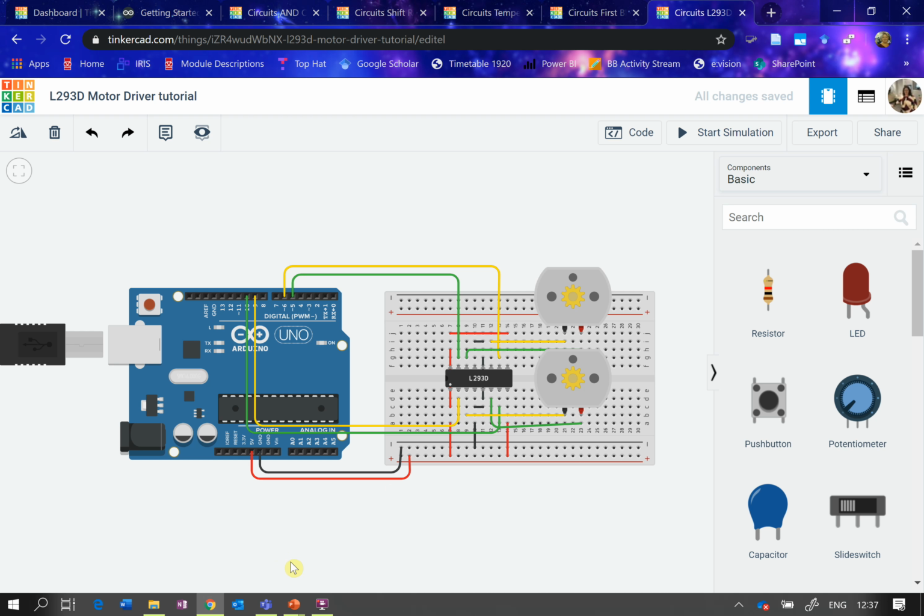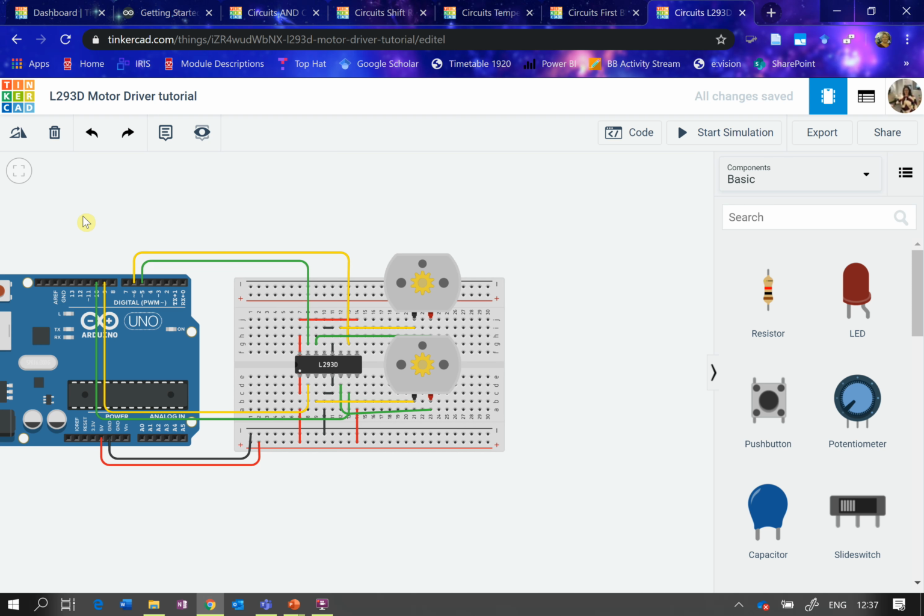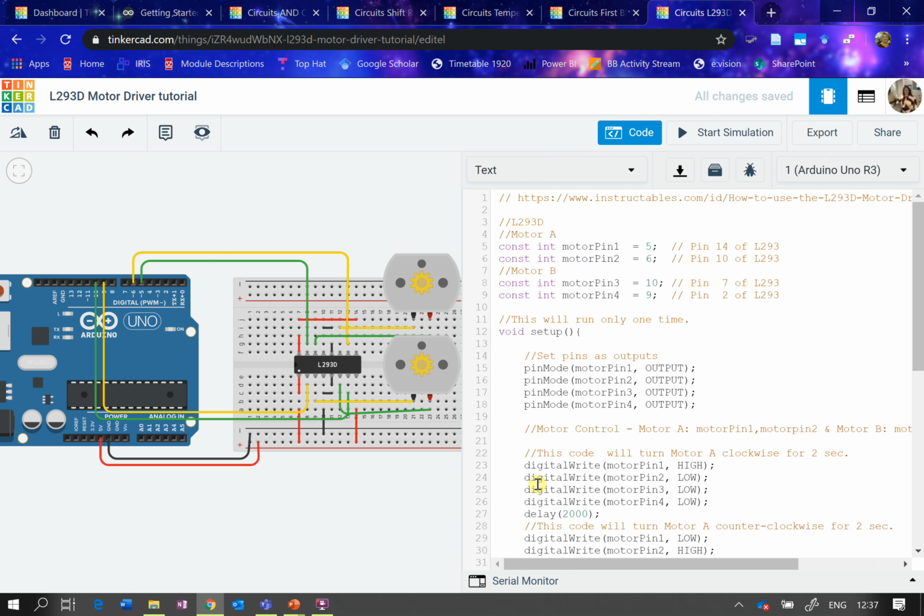However, I just want to show you that here we have a motor controller H-bridge driver, which can turn these DC motors in both directions. It's the H-bridge circuit from yesterday's first lecture. It's going to show the code, and we're going to move each motor in one direction, then the opposite direction, by outputting highs and lows to particular pins.